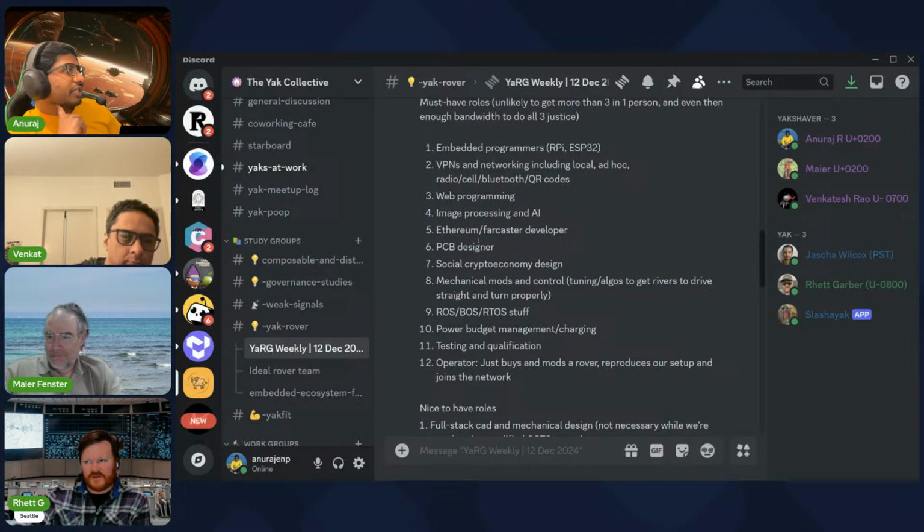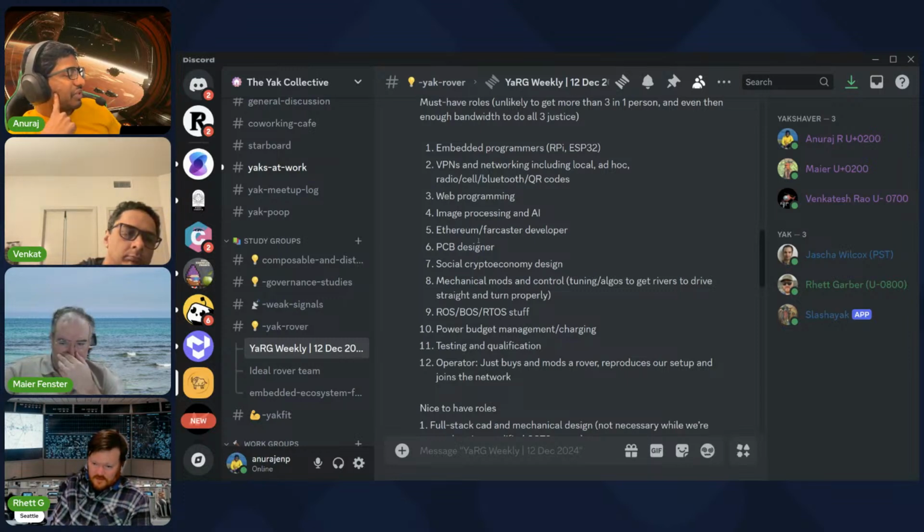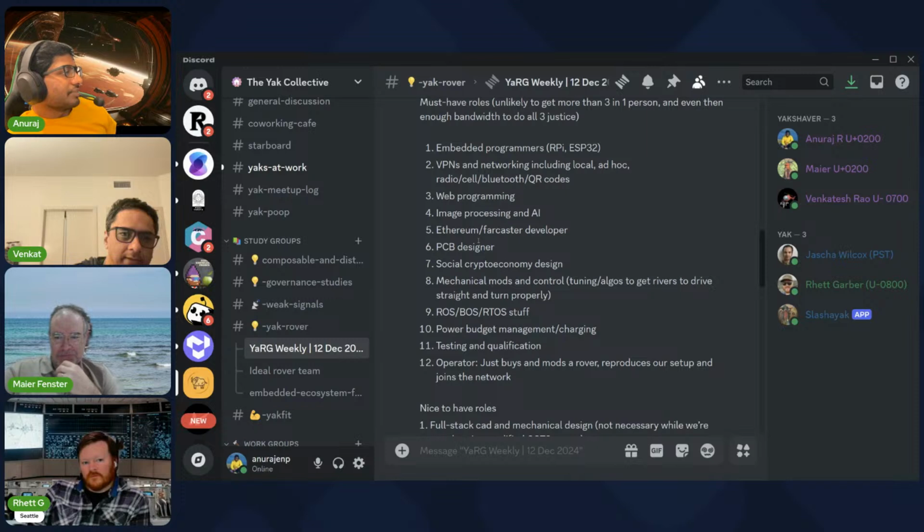And are those the encoders, I2C devices? Yeah, the temperature and humidity sensor, the ultrasonic, and the accelerometer are all I2C. And then the GPS is UART. Okay. And the encoders you have to connect directly to the pins. So with encoders, we could then have the Tumbler as a self-balancing robot if the encoders start working. And even if you don't use self-balancing, it's generally useful to have the encoder to track turns and distance and things like that.